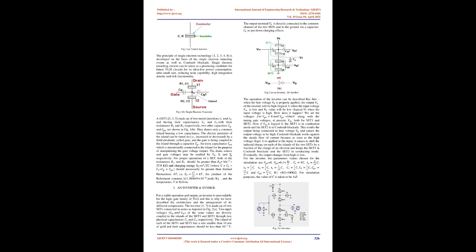When the capacitance of the tunnel junction is ultra-small, in the order of 10 to the power minus 18, the voltage building up in the tunnel junction will be adequate to prevent another electron from tunneling through. We will be able to suppress electrical current when the bias voltage being applied is lower than the voltage created in the tunnel junction.